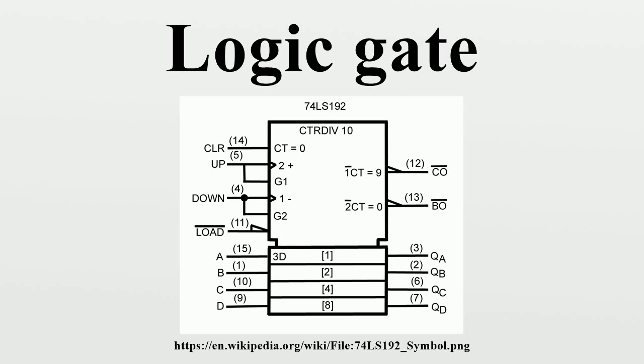This leads to an alternative set of symbols for basic gates that use the opposite core symbol but with the inputs and outputs negated. Use of these alternative symbols can make logic circuit diagrams much clearer and help to show accidental connection of an active-high output to an active-low input or vice versa.